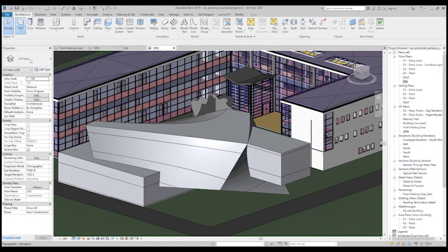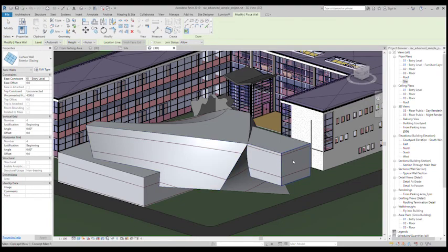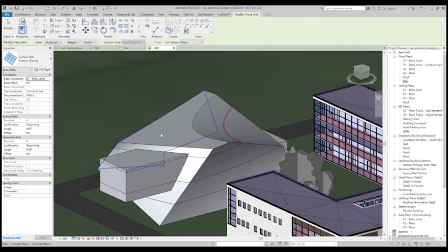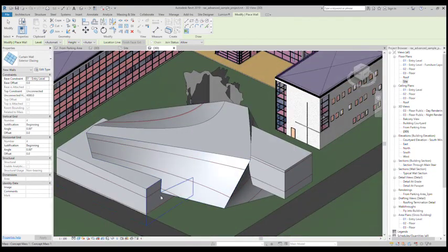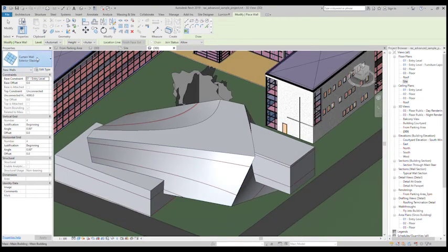That is the option where you can select faces inside your mass, any non-horizontal faces, so it won't select that roof, okay? And apply walls to it. And now there's two walls. You have solid walls, which are all of these under the drop-down menu under walls. All of these normal basic walls, which are just solid walls made out of different layers like brickwork, blockwork, concrete, insulation, and then curtain walls, almost like that in the example file where you have glass panels and mullions and transoms, as well as storefronts and pavilion walls.